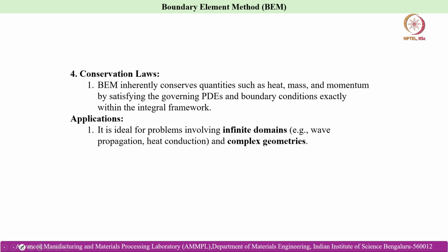And the conservation laws. BEM inherently conserves quantities such as heat, mass and momentum by satisfying the governing partial differential equations and boundary conditions exactly within the integral framework. Its applications encompass problems, as I told before, involving infinite domains such as wave propagation, heat conduction in a large area, and also complicated geometries where finite element formulation becomes too expensive and time consuming.